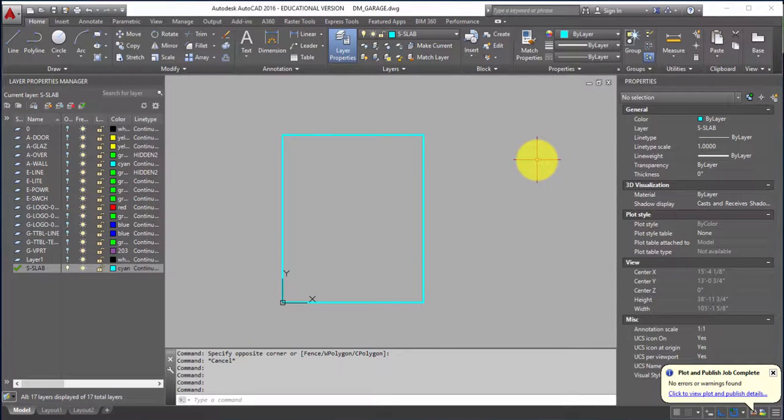I need to give some information now to the edge condition of the slab. In a garage, you need the wall to start 6 inches above ground, but you need the driving area of the garage to be lower than that. So in order to do that, I need to draw what would amount to a curb that goes around the outside edge of this garage.